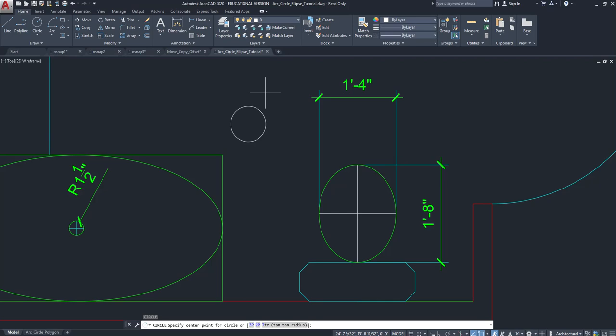And if I hit enter, AutoCAD reinitiates the command that I had previously been drawing with. So I hit enter, I draw another circle, escape. I hit enter, and draw another circle. That's something that will improve your speed. It'll make you very quick, right? I'm typing in commands, executing the command, and then I hit enter to reinitiate commands in sequence.